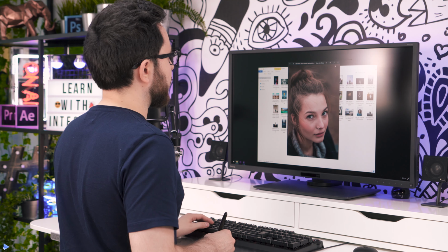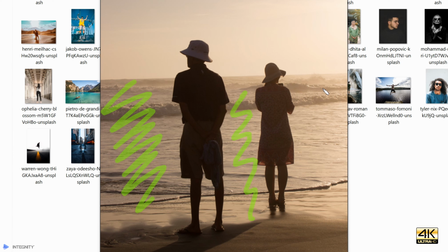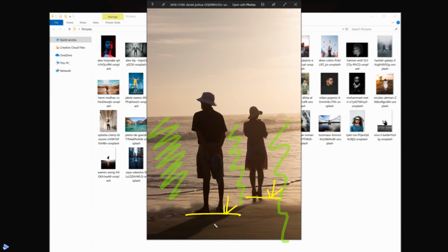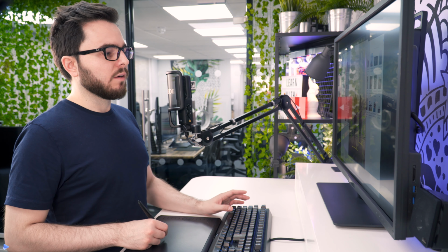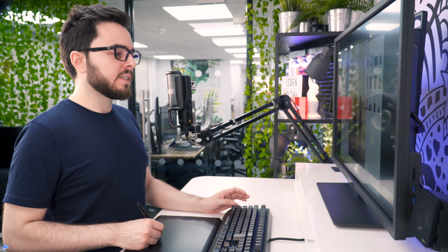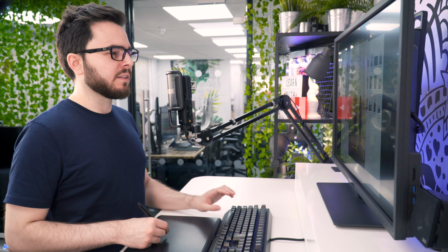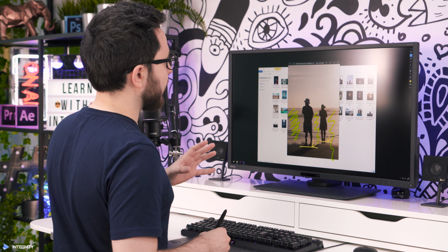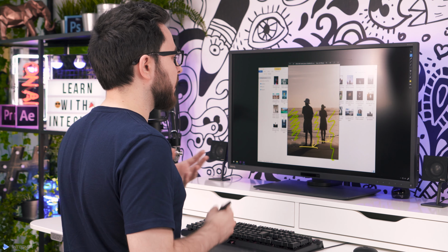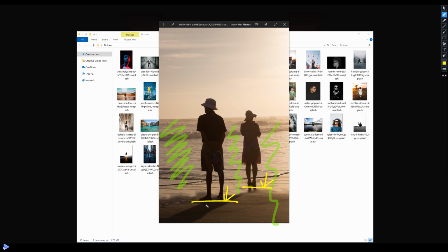This one, again, would be for horizon because you can see a lot of that floor going on. And obviously those people are standing on that floor, so you really want to pinpoint them to that specific location. If you used any other projection, for example parallax projection, you would see them floating in space and it wouldn't really look photorealistic. What horizon allows you to do is create that realistic depth in your images, especially when you have someone standing on the floor or touching a wall or something like that. So this one would be for horizon.